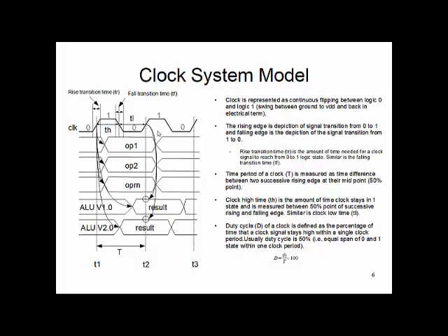It may be 2 clock periods, it may take 3 clock periods, but the point is that it's a fixed, previously specified time, and this is a handshake between the rest of the subsystem and the ALU in this example. This is an agreement that, hey, I am giving you input at this time point and I'll sample your output at this time point, which is a fixed time for the entire system.